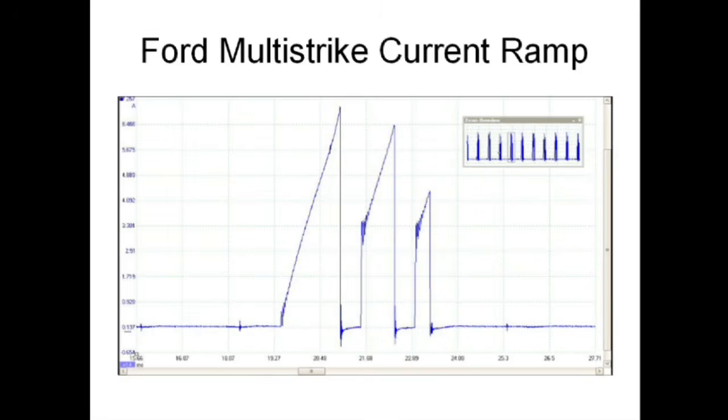We can see where the transistor turns on. If we measured the bottom of the triangular shape, we would get the coil saturation or dwell time. We have no vertical line, no big beer belly sticking out. We don't have a shorted coil. We can measure the overall amperage draw to the ignition coil.